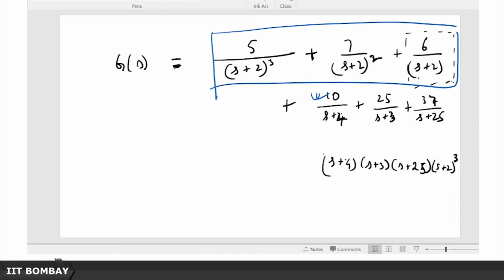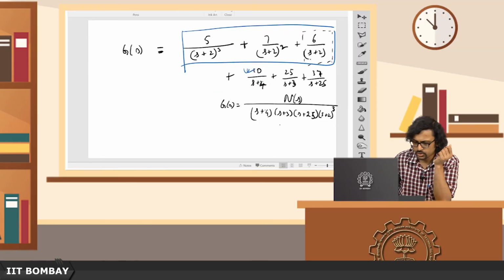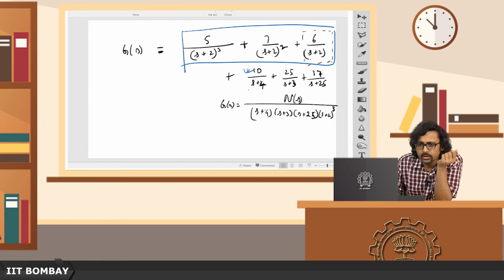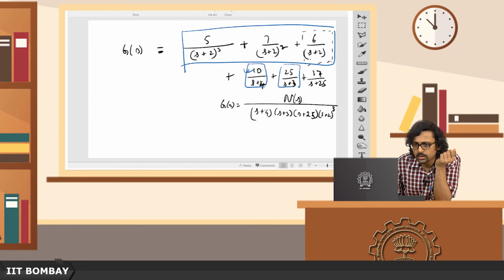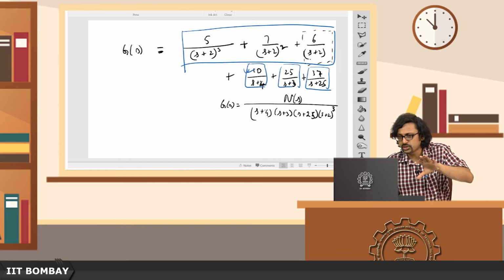So this is going to be my denominator polynomial for G(S), and some numerator sits over here depending on how these are weighted. Now you see that I have a 6th degree differential equation, obviously, so I will need 6 integrators. 3 of the integrators I have used up for this block and this block, and now for the remaining 3 blocks I have to use 3 more integrators.